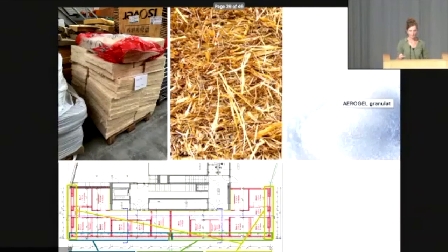And then it was a great opportunity for us to experiment and test. So we actually reused our own facade systems that we had developed in these previous projects. We reused them, and then here we put in other rock wool. This is rock wool from the EMPA itself. We put in straw bale again, and then aerogel. That's like a deal that the EMPA wanted to test. So we did the same facade and added these different insulation materials, and we can now test and measure and understand the results of these different insulation methods.